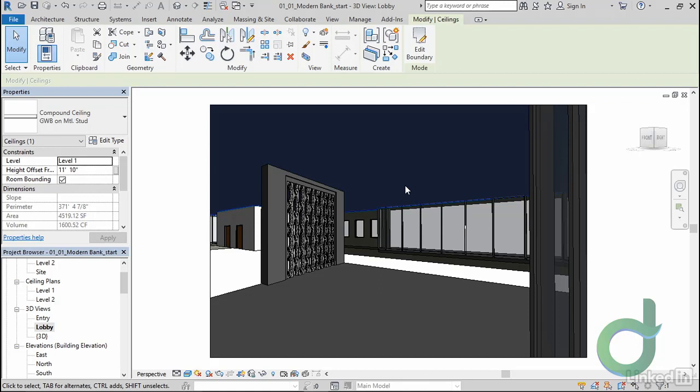So I'll tag this one as needing some attention, especially before I start punching holes in it. We also want to consider the lighting conditions on the inside. A ceiling like this, and the soffits on the outside. Most likely though, if we're trying to show a realistic view, this ceiling is going to be hit by all bounce light. And so this large mesh gives us the distinct possibility of many blotchy rendering artifacts if we're not careful. So it's wise to break up this as well.